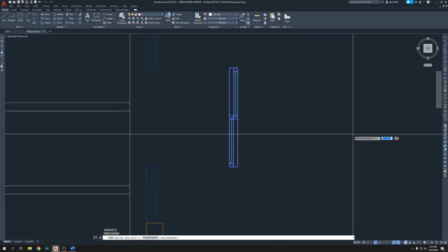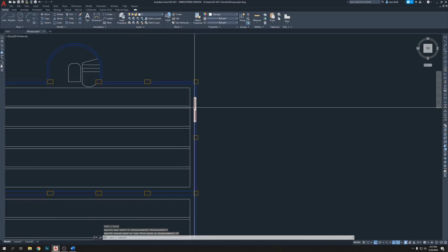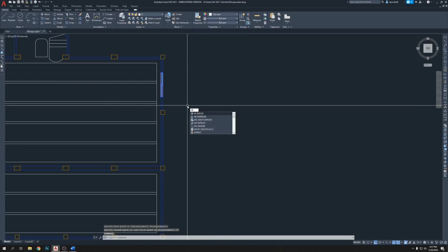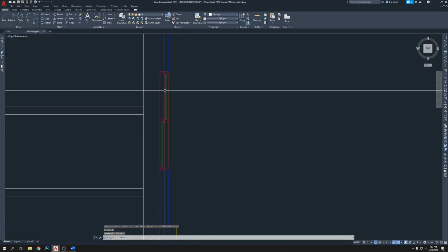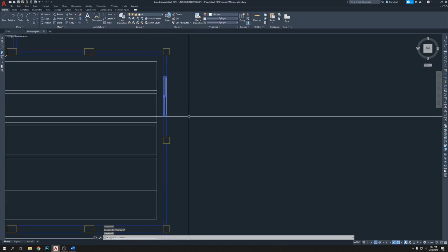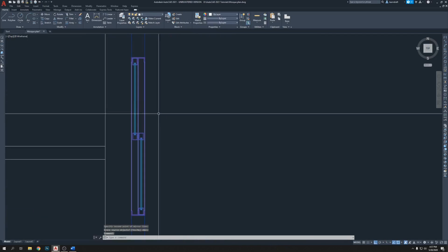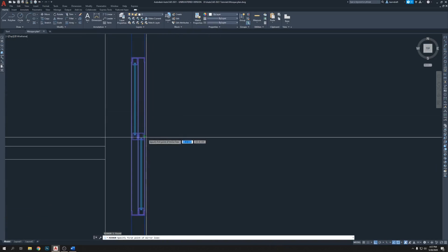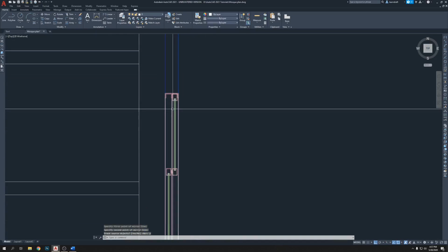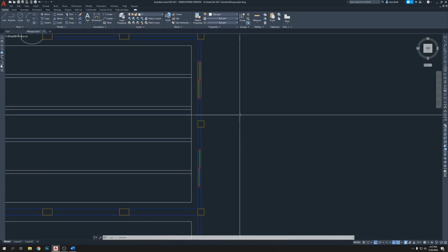Select, move command, click 5 feet, enter, and then select this one. Can't do mirror. If you do mirror, this thing gonna go mirror, but that's the easy way to take it. But then we're gonna mirror it again. MI, enter, select here to there, and then we mirror this one on the spot from center to center. So it's going to be this panel out, this panel in, this panel out, the same way. I hope you understand what I'm saying.